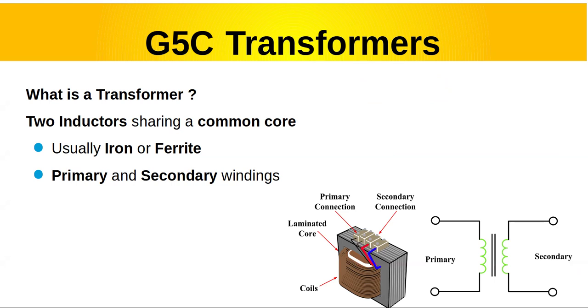In old tube type equipment, you would have a power transformer that would have a primary where you put 120 volts in. You'd get 6.3 volts on one side for filaments. You'd get a high voltage, maybe 400 volts for the plate voltages, and you might get 100 volts or something for screen voltages. You don't see too much of that anymore. Even in the tube type power amplifiers, are usually grounded base triodes. You'd only have one high voltage and a filament.